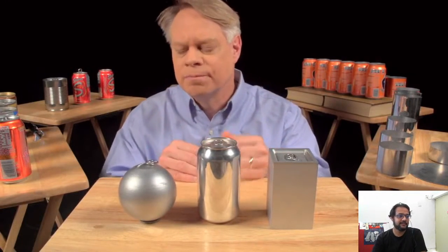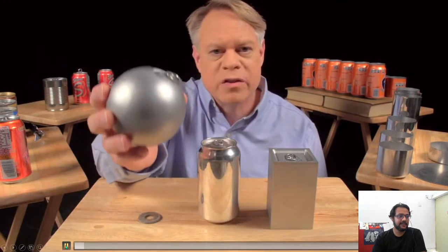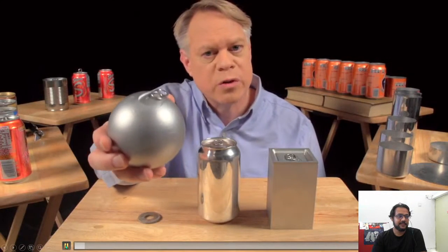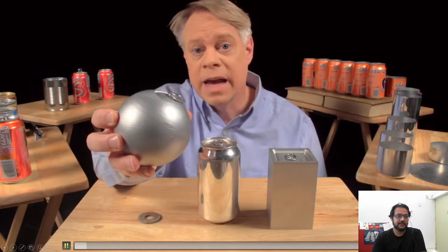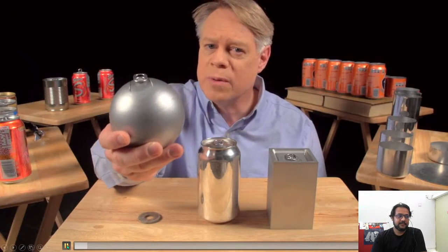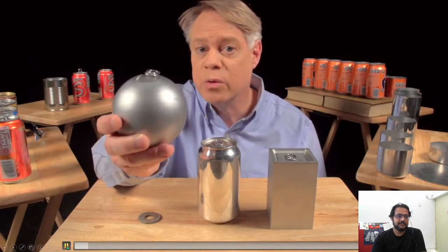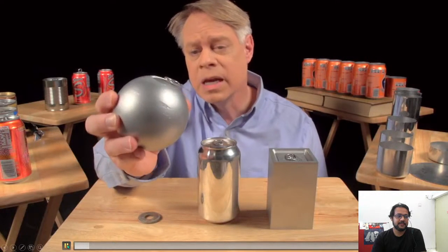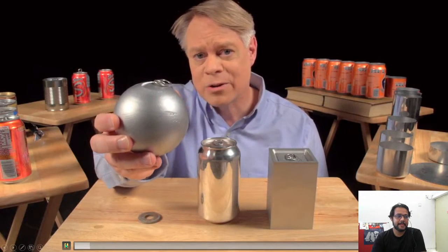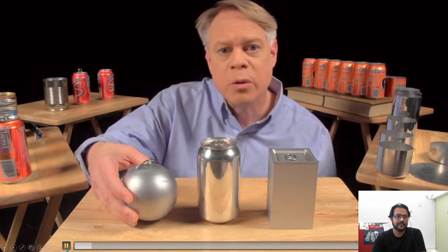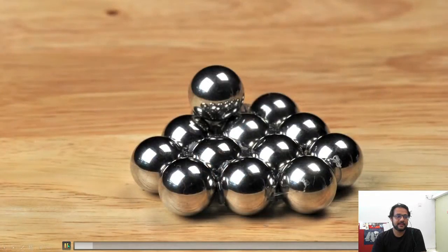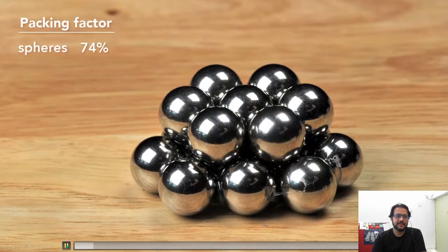Why a cylinder? An engineer might like to make a spherical can. It has the smallest surface area for a given volume, and so it uses the least amount of material. It also has no corners, and so no weak points, because the pressure in the can uniformly stresses the walls. But a sphere is not practical to manufacture, and of course, it'll roll off the table. Also, when packed as closely as possible, only 74% of the total volume is taken up by the product.